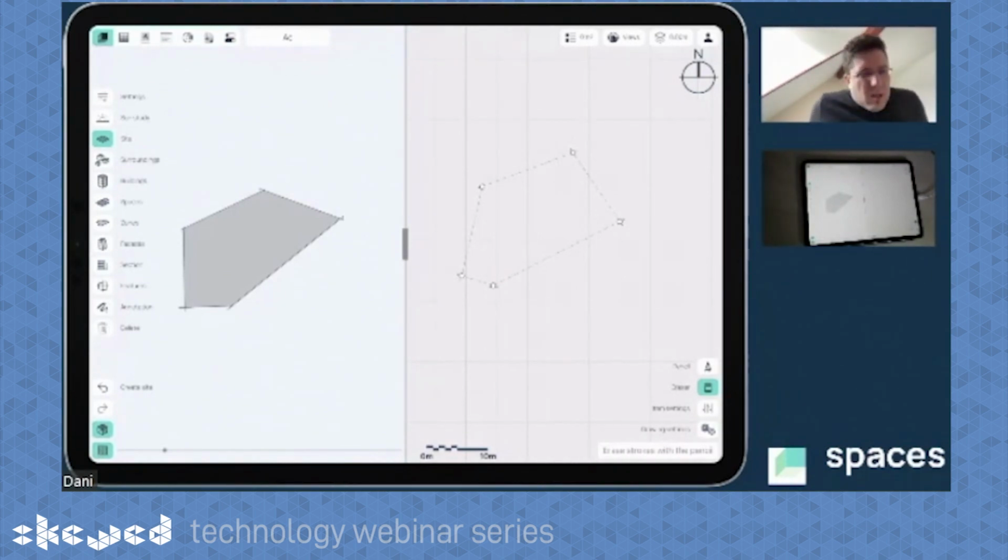Zate, brilliant app. Do the areas, when imported from IFC to ArchiCAD, automatically become zones? I will take that. In Spaces, these areas are called spaces, and these are transferred as ArchiCAD zones via IFC. Also, the other three-dimensional elements Spaces uses, like columns, are transferred to proper IFC columns as well. And as mentioned in the demo, Spaces contains not just the physical shape of the body, but the usage type and other available metadata that you can put in here. It will be exported to IFC too.